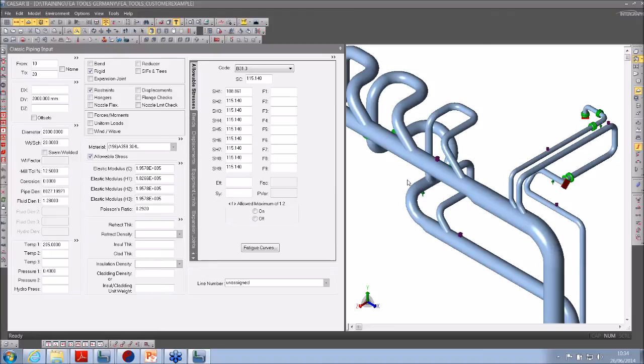In addition, we also have large diameter and thin wall piping. The D/T ratio is very high. So in some places, the D/T, diameter over thickness ratio, is over 250. And note 11 of Appendix D, which I pointed to in the presentation, states that the intensification factors are valid for a D/T of less than 100. So we're considerably higher than that.